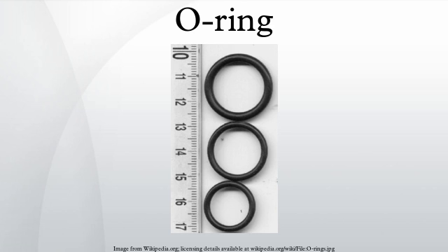Swelling by contact with a low viscosity fluid causes an increase in dimensions, and also lowers the tensile strength of the rubber. Other failures can be caused by using the wrong size of ring for a specific recess, which may cause extrusion of the rubber.